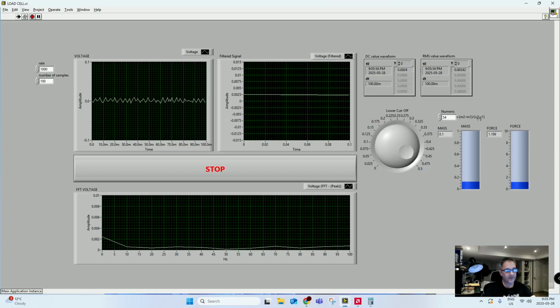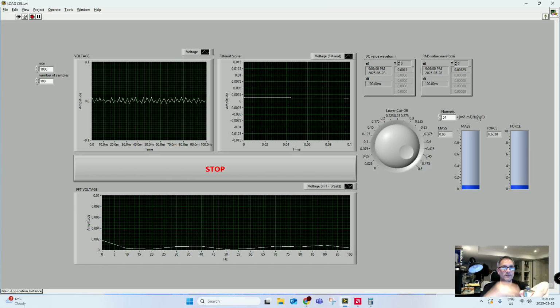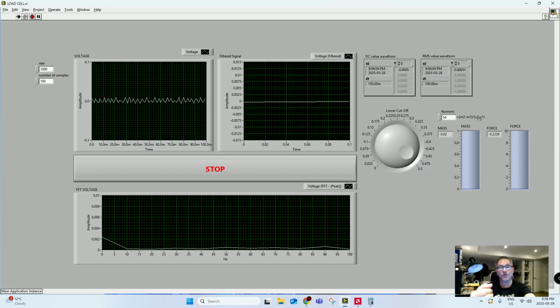these particular characteristics. What happens is that if I remove the jam nut and I let this component go down, the thread is sucked up, so it deforms the strain gauge. But if I put the jam nut and then put the thread in traction along with this, the resultant is zero and the plate is not deformed, so the strain gauge captures only the weight of the part.